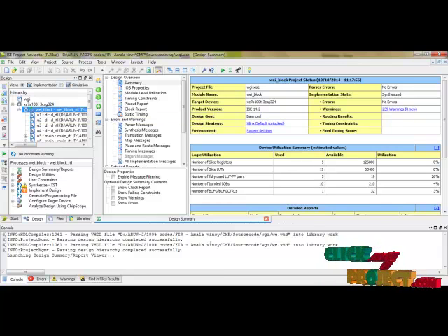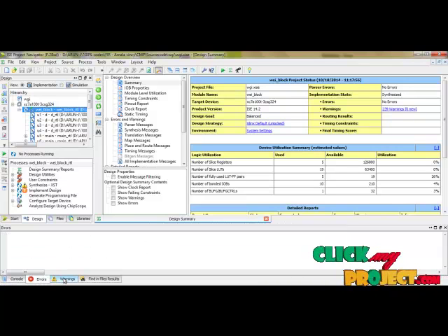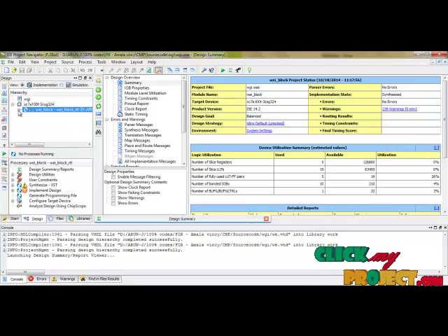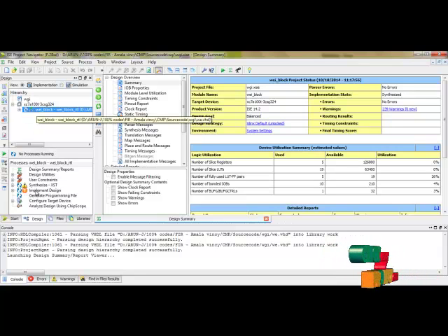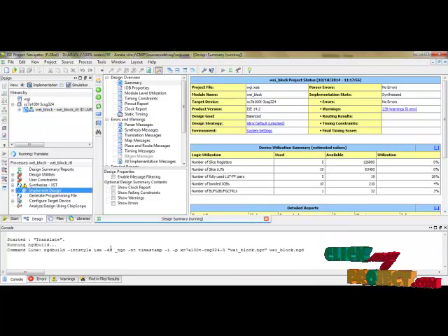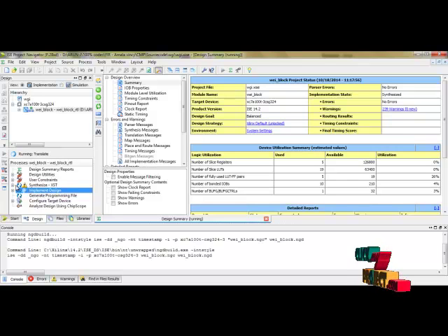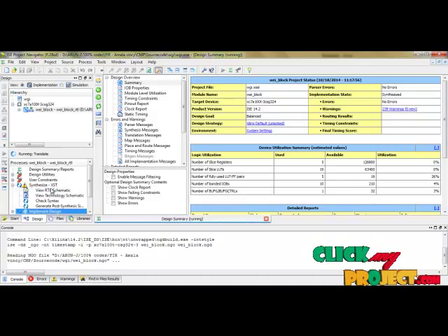This is the synthesis report block. Here you can see the modules and the files. The console shows the running process and what is happening during the run. For example, if the run is completed successfully, it will show that. It will show the errors during the program, and this will show the warnings. I have selected the main module. To run the process we have to select the main module, and I am implementing the design. Initially I have selected the implementation, and by selecting the implementation only, I can process the implement design. Then we have to go for synthesis.